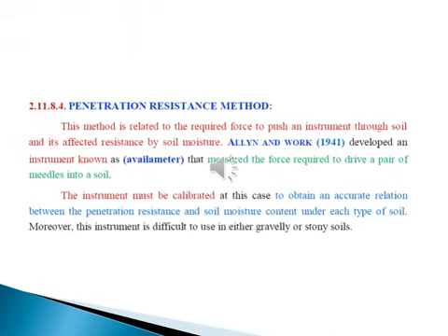The penetration resistance method is related to the force required to push an instrument through soil, which is affected by soil moisture. Take into consideration, please, that in this case the instrument must be calibrated to obtain an accurate relation between the penetration resistance and soil moisture content under each type of soil.